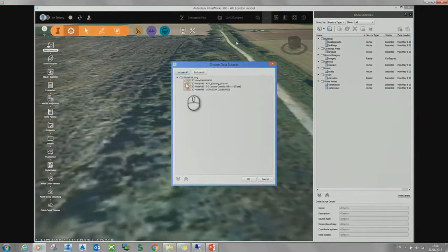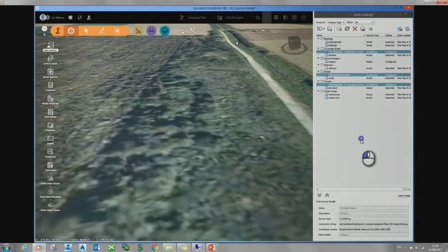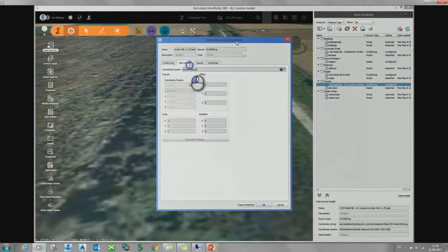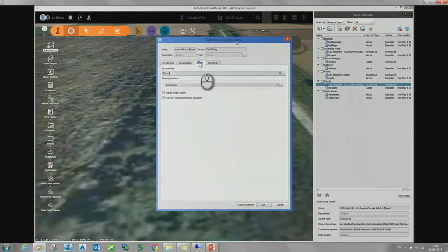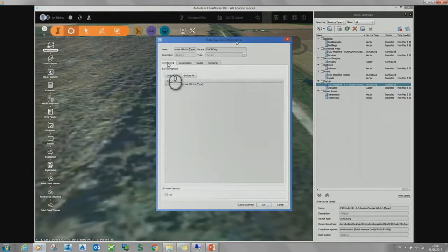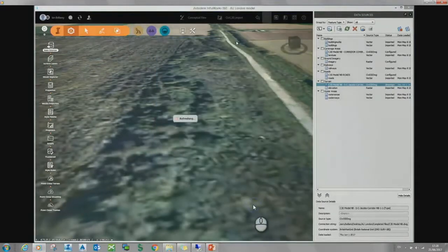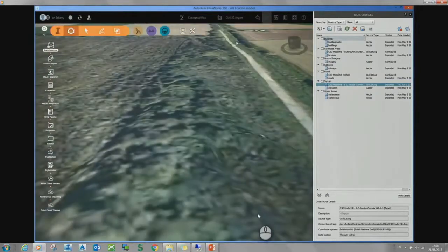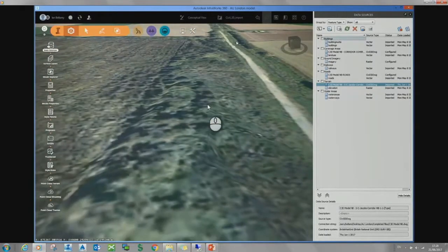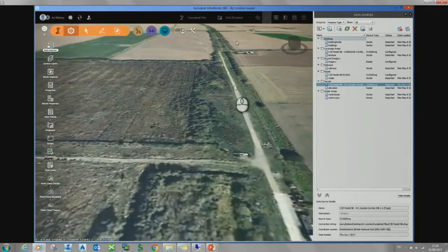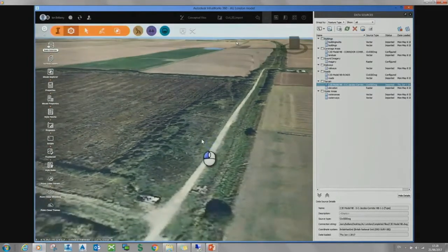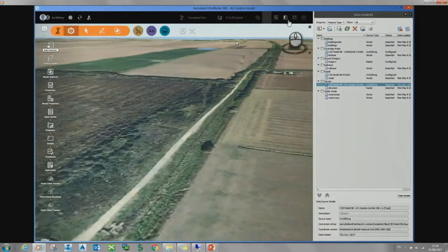So in here you can see it's got everything that's in there. If we untick this surface, because we don't need the existing surface at the moment, and it's brought in an alignment, a terrain, and some coverage areas. So as we did previously, set the terrain model to national grid, and close and refresh. And this is effectively doing the automatic version of what we did manually, using the 2D polylines and the 3D polylines. So you can see there, we have the surface brought in.